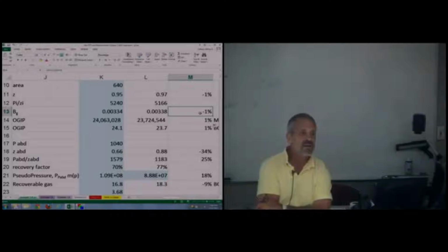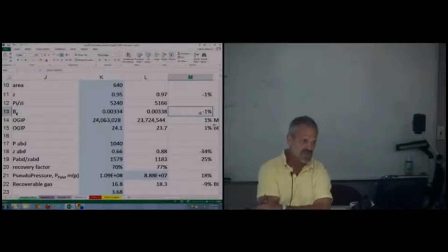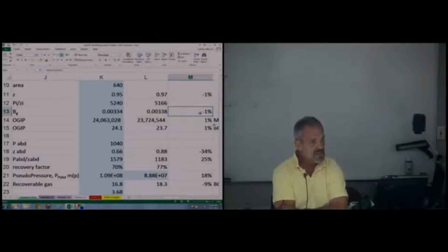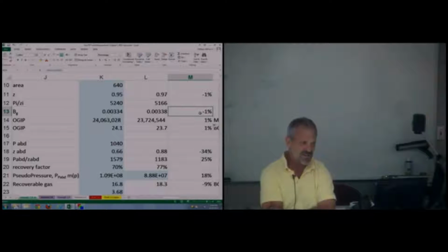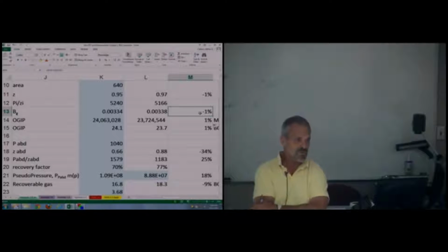Now for a real gas, it's equal to 1 over pressure minus 1 over Z dZ/dP. So that is the compressibility. It's a function of Z, and it's a function of the slope of Z as a function of pressure. And so Z is sometimes referred to as the supercompressibility factor, but people don't like to use that word super, so sometimes they just call it the compressibility factor. But it's not compressibility. Compressibility is approximately 1 over pressure. And for an ideal gas, it is equal to 1 over pressure.